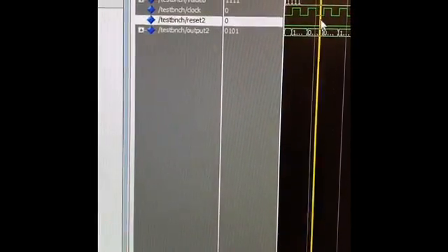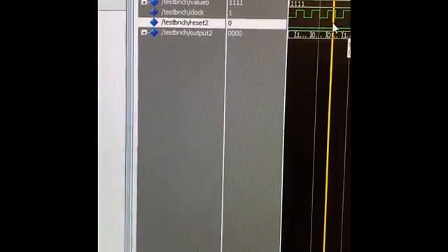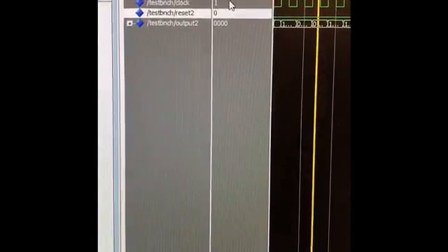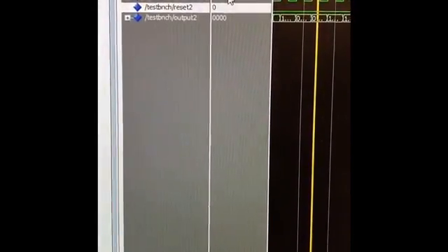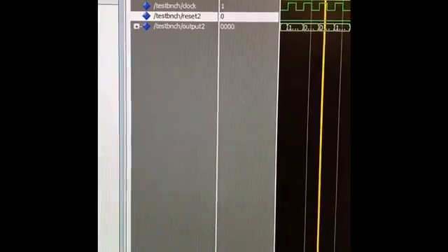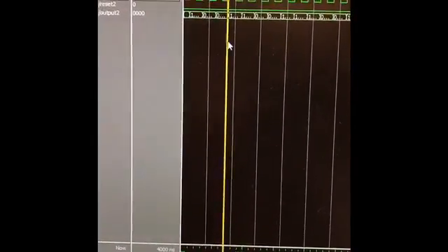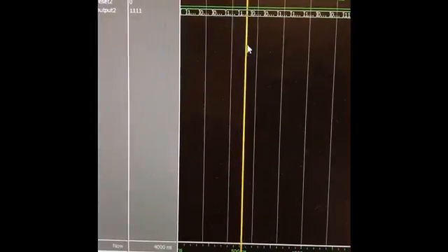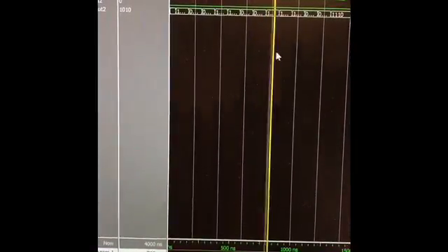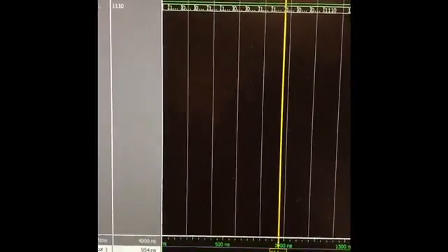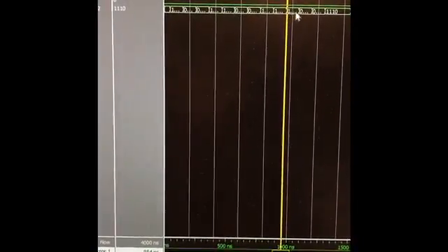For the last state, on the positive edge trigger, it should be a NOR function, which means it should be the opposite of our OR function, a not OR. So that means if there is a 1 in the equation, out of the 2 bits, then there should be a 0 as an output, which we see here, 0. So we're going to test our next states. It's going to continue to go through each state, so this should be the AND, OR, XOR, NOR, AND, OR, XOR. So when they change, we should expect this to be the XOR output because we're going through the states.